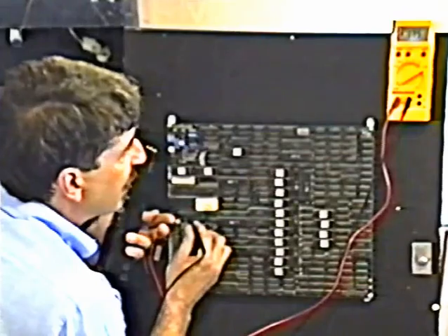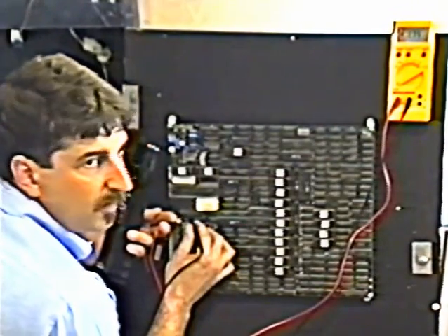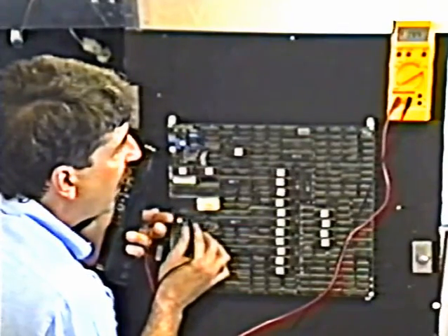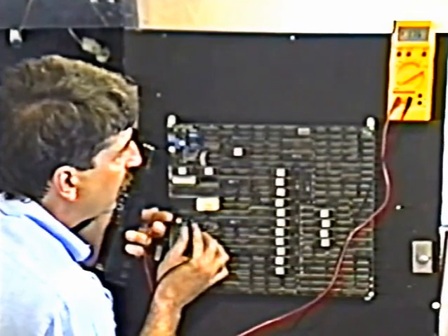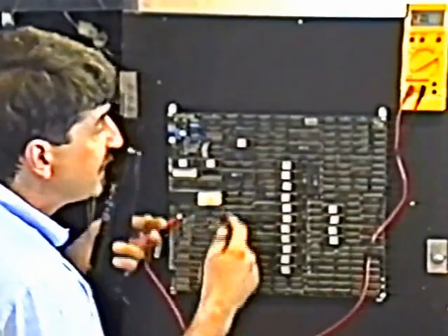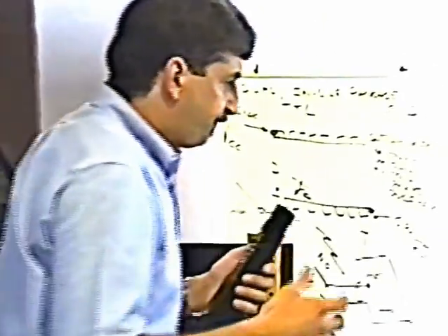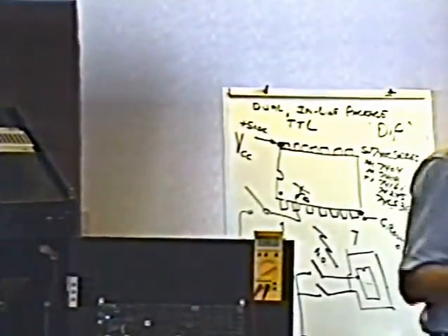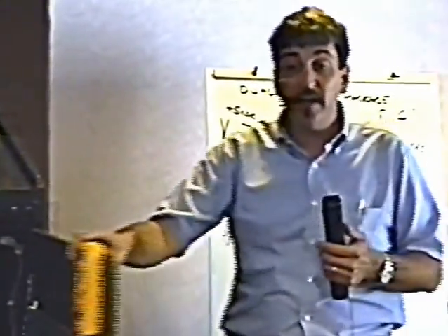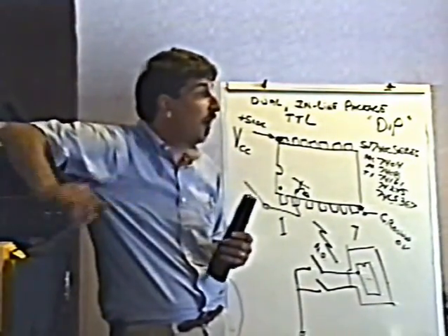Oh. Like this. You see it says like 0.17 is what the meter's saying right now. I'm having a little trouble holding it on there. That's much lower than 0.5, obviously. And you may see something like 0.05, or it may say, you know, dead short or whatever. When you get to the bad integrated circuit, that pin will be much lower than all the other pins.